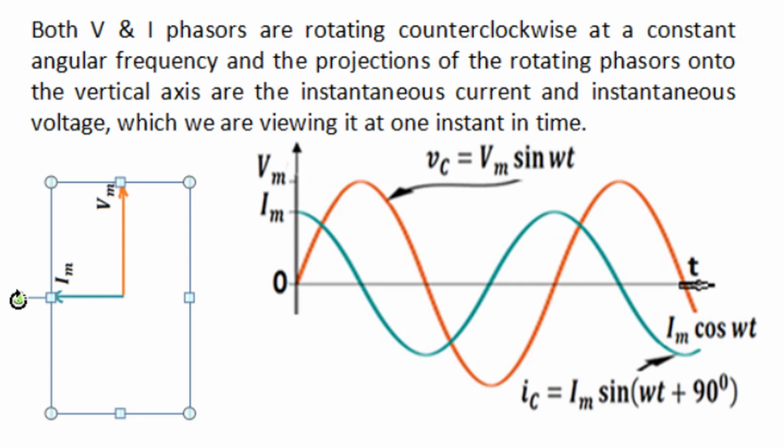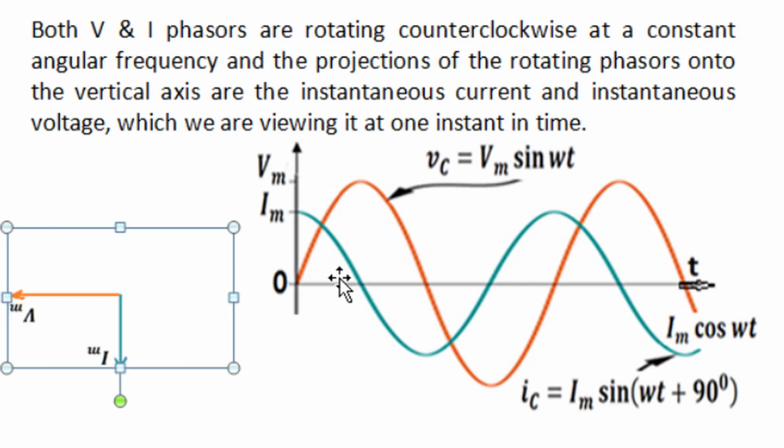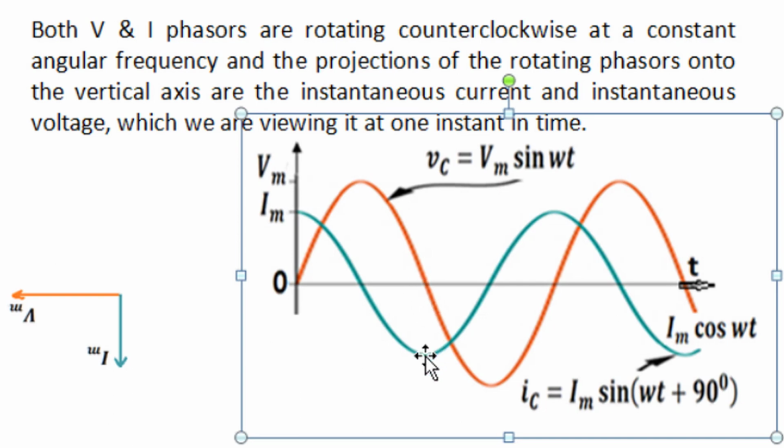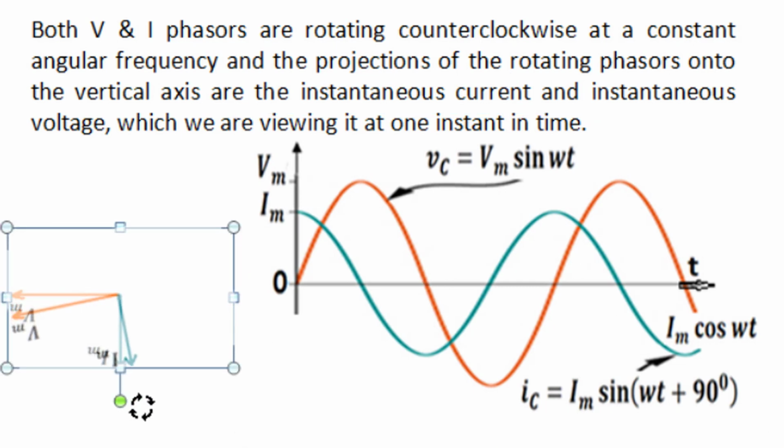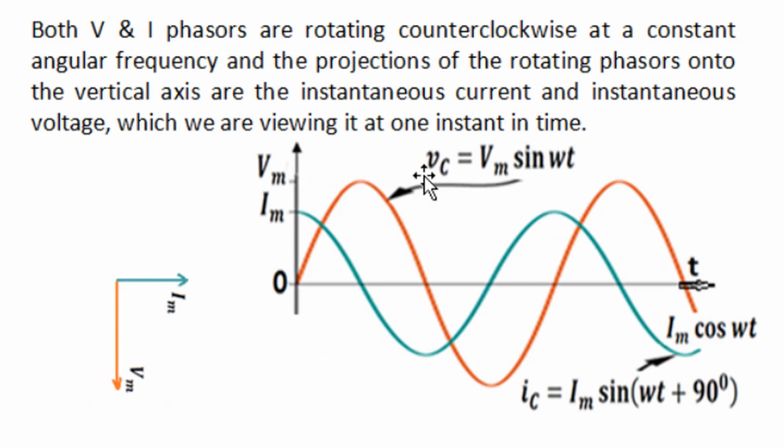continuously increases. It represents that charging current is decreasing and charge and voltage across the capacitor by charging is increasing. Further rotation of the phasor alters the sign of current and current becomes discharging current, and the projection of voltage on the vertical axis decreases. That means discharging current reduces voltage and charge on the capacitor, and at this time instant discharge current becomes peak negative and charge on the capacitor plate becomes 0. Further rotation reduces discharge current magnitude and increases voltage with opposite polarity on the capacitor plate as shown by the phasor diagram, and at this instant discharge current becomes 0 and the capacitor will have negative peak charge and voltage across it.